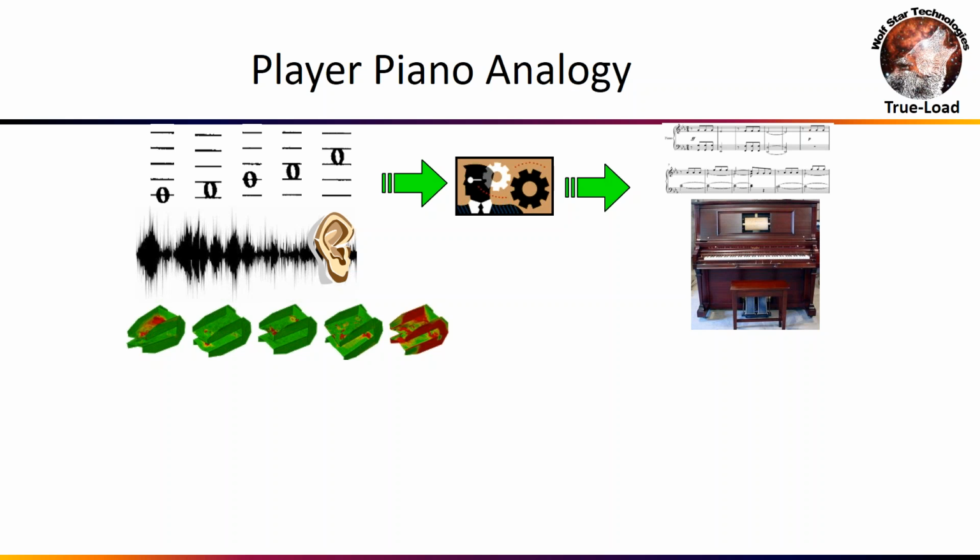We'll take our component part, and we'll put a series of unit load cases on our component part. Then we'll create strain fields on the part. Once you've got the strain fields on the part, TrueLoad will look at those strain fields and identify strain gauge placements to identify each of the strain fields uniquely. So we'll get a strain gauge pattern that will uniquely identify each of these strain patterns. And then we'll store that correlation matrix to the disk.